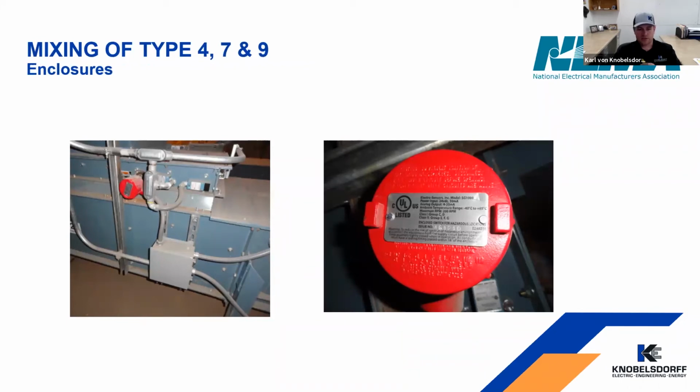Here we got a few pictures of some different equipment. You may see this where you've got a mix of type 4, 7, and 9 enclosures on the same equipment, which can be perfectly fine by code. So here I've got a type 4 junction box, just a dust tight junction box that likely has no splices behind there, which would pass in a Class 2 Div 1 location. Then I've got some NEMA 7 or 9 limit switches, as well as a position transmitter off of a gate, which would need to be listed for a Class 2 Div 1 and use that NEMA 7 or 9 rating. But the box I'm just using as a pull box can be rated NEMA 4.